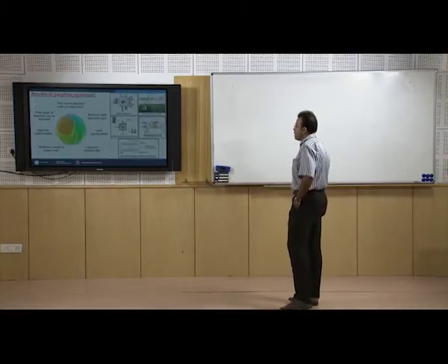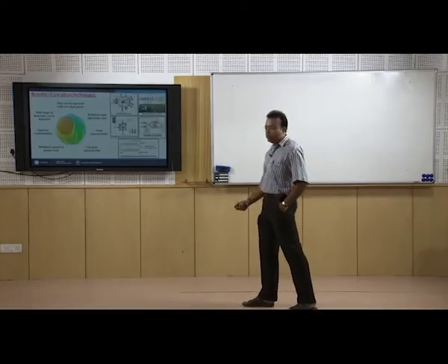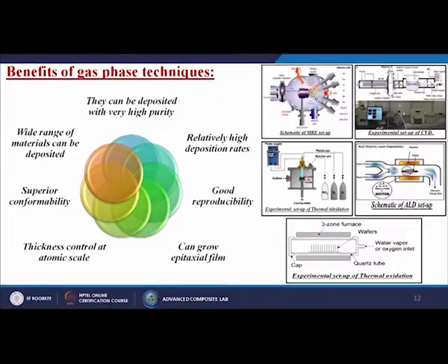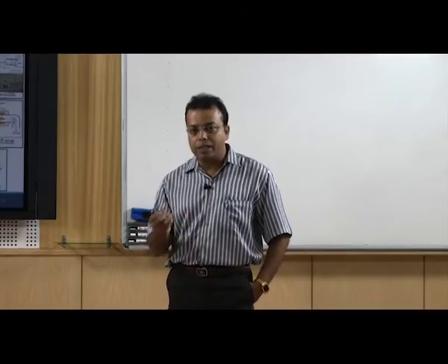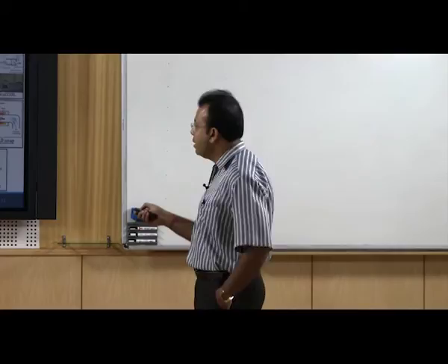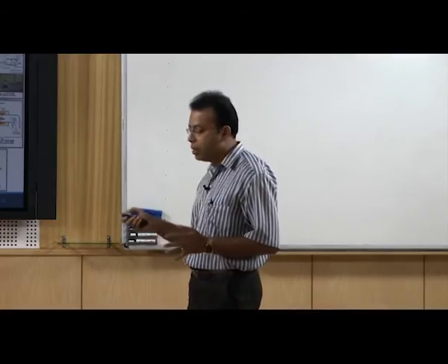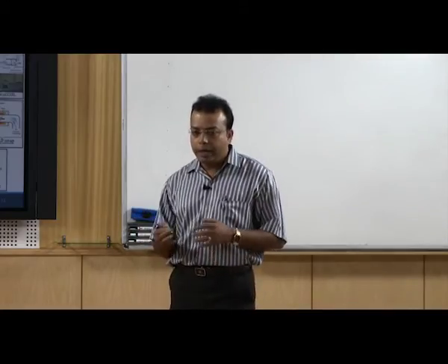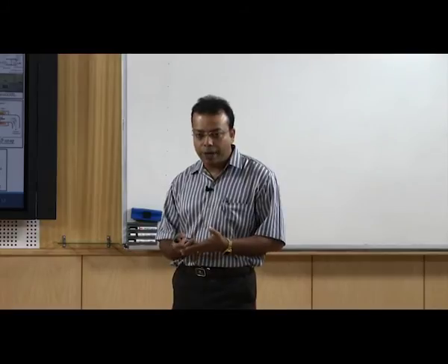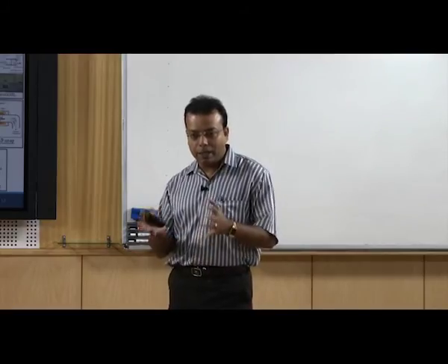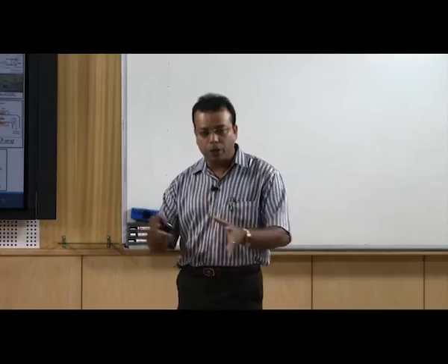Benefits of the gas phase techniques. There are lots of benefits we can get from these techniques. What are those? First, they can be deposited with very high purity. So, here the incorporation of impurities is very low. Then relatively high deposition rates, because it is controllable. It depends upon the gas flow rate, it depends upon the target materials, and it depends upon how much energy I am putting onto the target material.